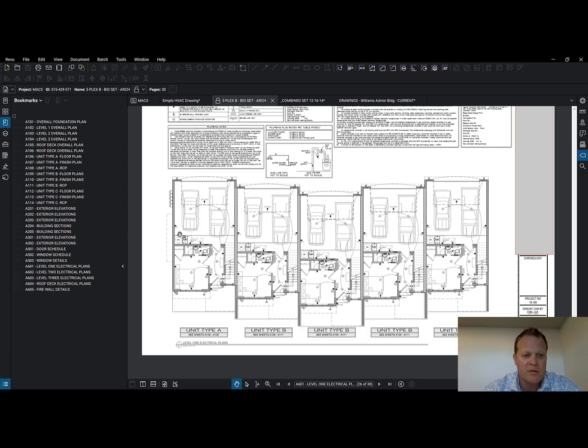We cannot be running screws from drywall. We cannot be running nails from base into these locations. Protect this area and really pay attention when we're doing these. It would be a bad day if you had a bunch of refrigerant lines spread everywhere and were getting nails or screws into them. Be no fun. And to say, hey, we put the plates over it, that doesn't stop anybody from shooting a base or a trim nail right into your refrigerant line.